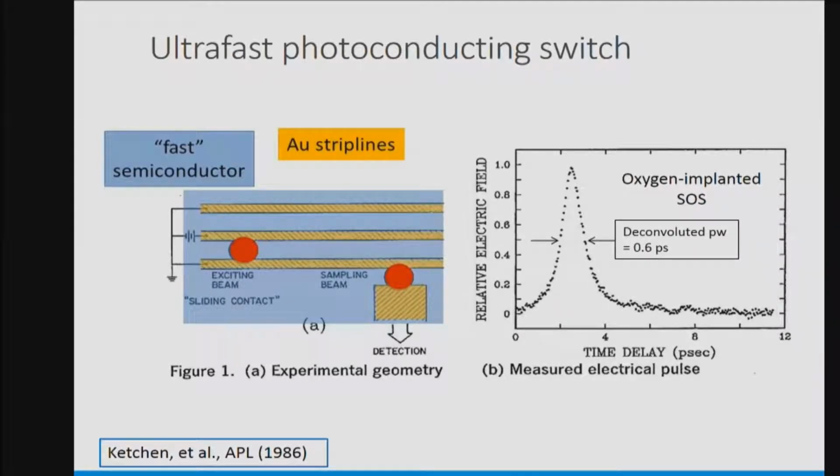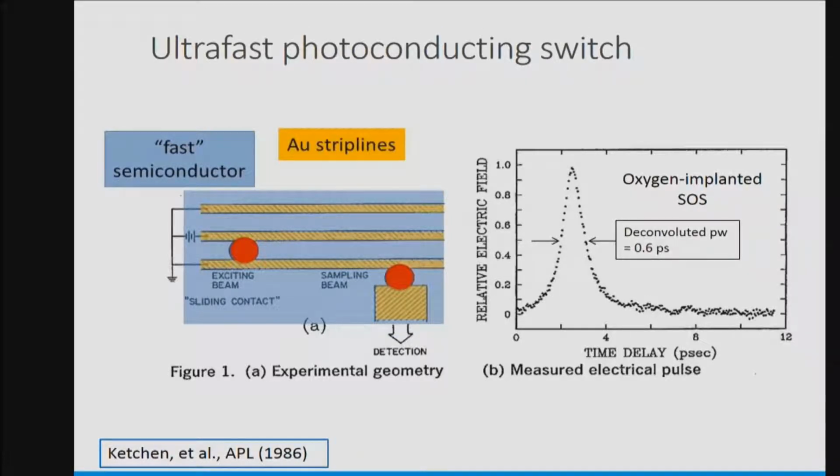The measurement is just done right here using the same idea. You have, again, a semiconductor photoconducting switch where you just sample a little bit of the electric field that arrives at this part of the line, send that into essentially a low-frequency detection circuit, and as you vary the time delay between these two pulses, when the pulse just arrives, you get current flowing in here, and this is a high repetition rate experiment, so you get DC current going through here.